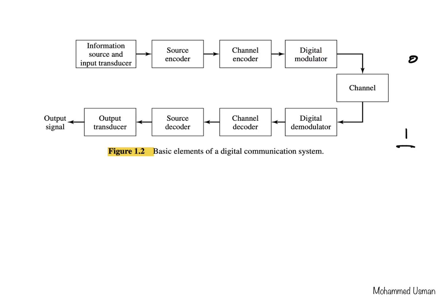So we have a digital modulator, and again, like in the analog modulation where we had AM, FM, and PM, there are several variants of digital modulation. Like the digital equivalent of AM is amplitude shift keying, ASK, and for FM the digital equivalent is FSK, and for PM it is PSK. And furthermore, in digital modulation we can have higher order modulation schemes, whereby we can represent more bits in a single symbol, so that increases the bit rate. Okay, we'll come to those aspects later.